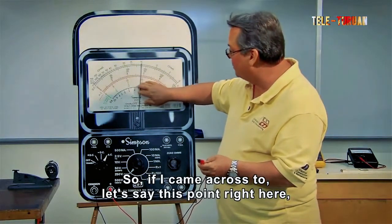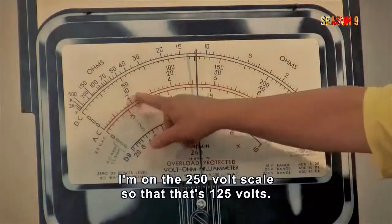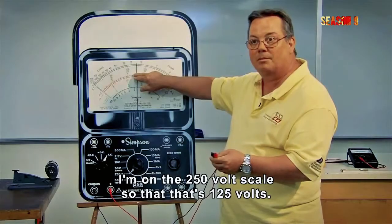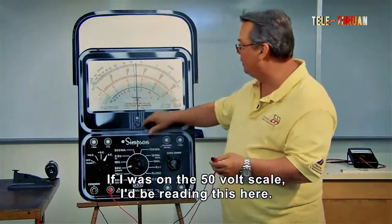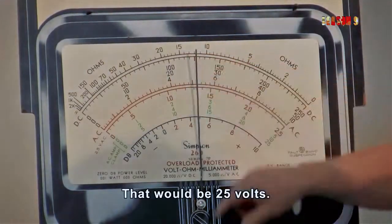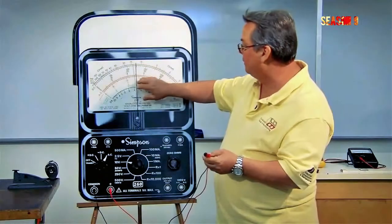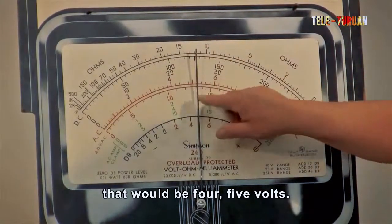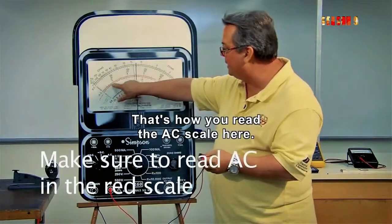So if I came across to, let's say, this point right here, I'm on the 250 volt scale, so that's 125 volts. If I was on the 50 volt scale, I'd be reading this here, that'd be 25 volts. And if I was on the 10 volt scale, I would be reading down here, that would be 5 volts. So 5 volts total. So that's how you read the AC scale here.